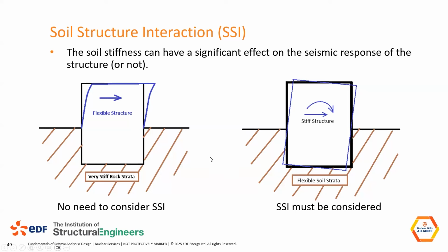But SSI is important. This is what you're doing. You're considering, does the soil affect the response of my building? If it does, I need to consider it. Otherwise, I'm missing a very important mode shape.